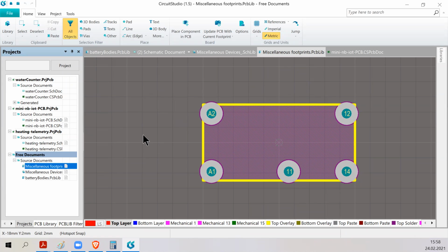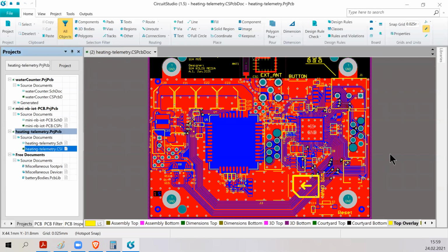So this is why usually the board has this low frequency oscillator for timekeeping, for precise timing. But for other tasks, usually the internal oscillator at high frequency is sufficient. But if you need both clocks precise, then of course you would use both of them in a precise manner.